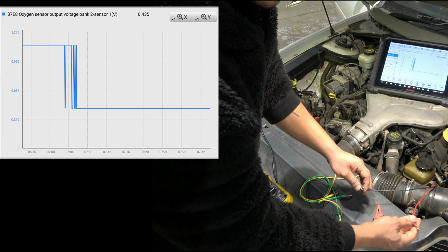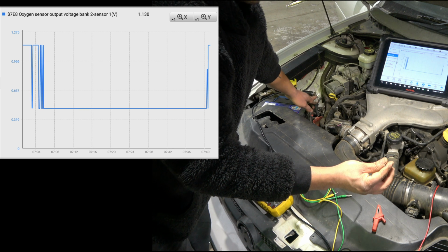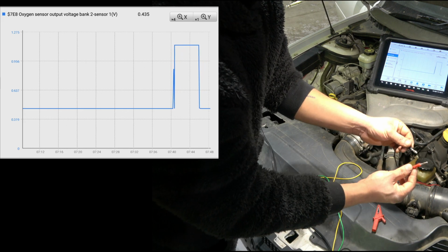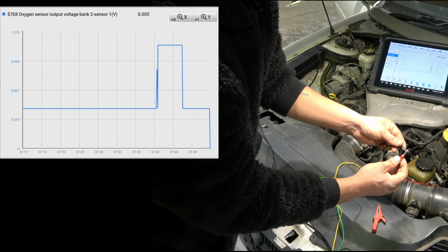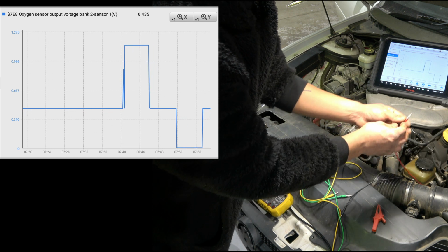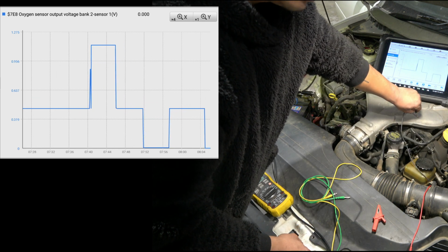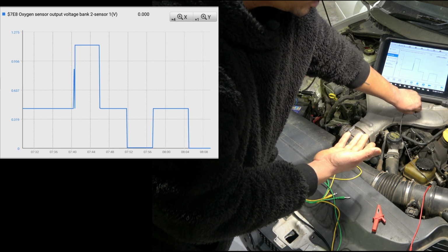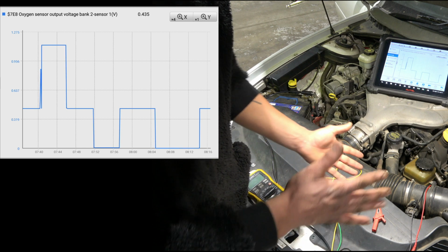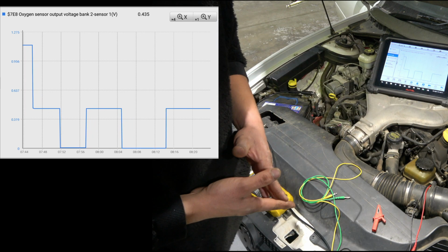Okay, we can do it again. We can drive this signal up by touching the positive side of the battery with our body, or we can join this wire together, just shorting out the earth, okay, like that, and we can drive that to 0 volt on the scan tool. Or you can always just touch the body of the car. It does the same thing. Sorry, that's not the signal wire. This is the signal wire, the black one. Touch the body of the engine. Basically, we're supplying earth. Same thing, we got earth on this wire too. It's the same exact thing. And it dropped to 0 volt. Okay, it verifies that the wiring is good, computer is good, computer is reacting. Basically, the oxygen sensor is the problem in this car.